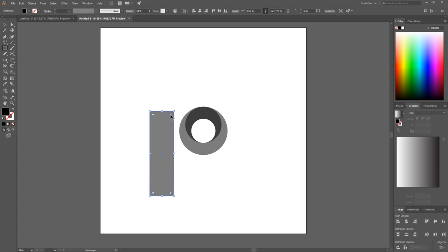And over here on the inside of this rectangle, you'll see these little round anchor points. I'm just going to click and drag that in until those edges turn red like that, and then it's going to become rounded. Then I'll grab the Select tool. I'm going to hold Control on the keyboard, grab this node right here, and then just snap it to the left side of this inner circle right there, just like that.